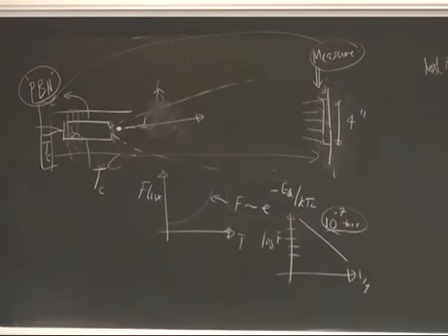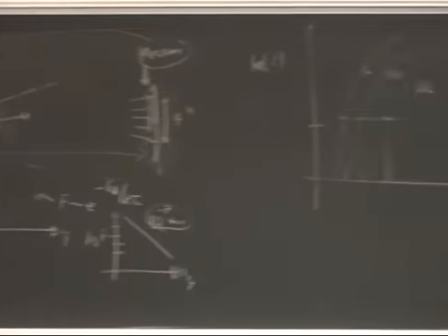So there's a lot of work that goes into designing the flux, the angle at which the atoms come out, and depending upon the geometry of the crucible itself, if you have a rectangular or rather cylindrical crucible, you'll have this. If you kind of make it at an angle here, I think you can physically, intuitively see that it should spread out a little bit, right? Maybe, yeah. And you can calculate all these angles, of course. And then this sort of design goes into the amount of stuff that deposits, or the uniformity on the wafer will be something like that, what's shown here, for example. Right? And this part we'll discuss again when we talk about the growth in detail.